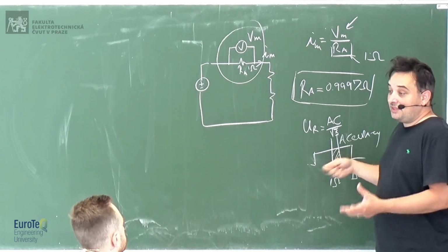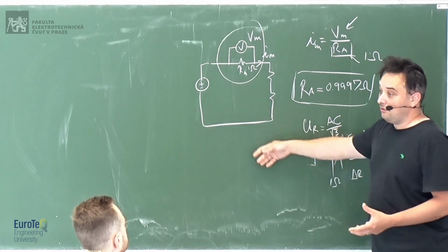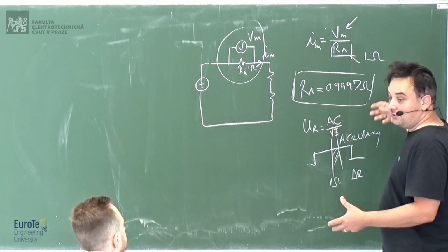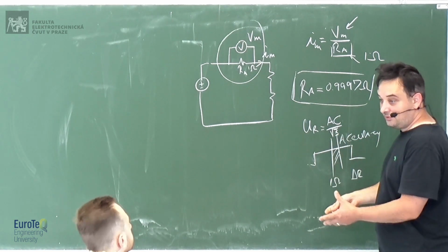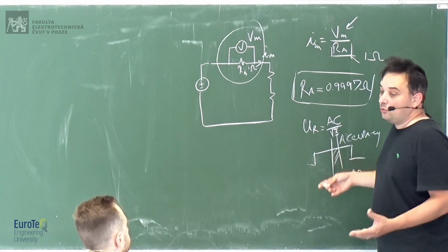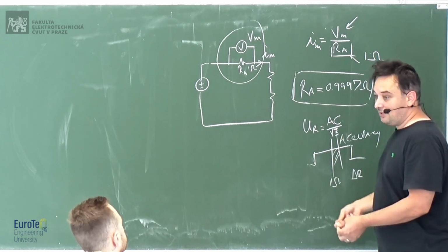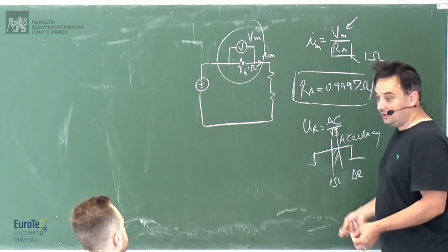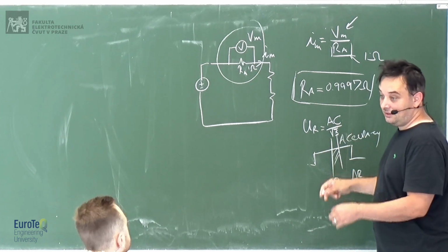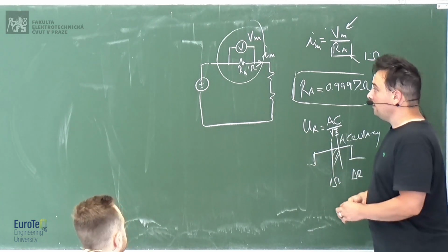Again, you always have to make some assumption. In this case, you assume that the statistical distribution of those resistances is equal to that of the batch that was tested. You have to declare it. Otherwise, you take that single resistor that you're using and calibrate it, so you measure it, calculate the uncertainty of your calibration, and then use specifically that value.